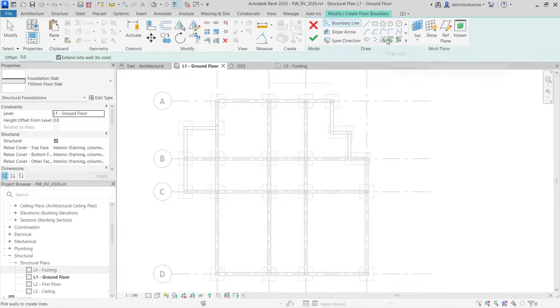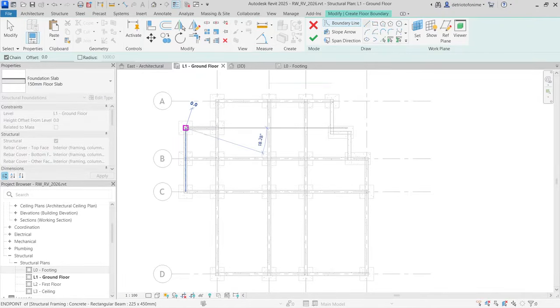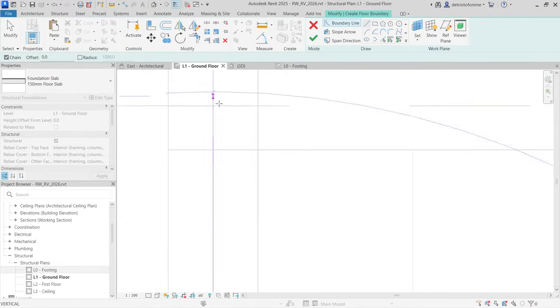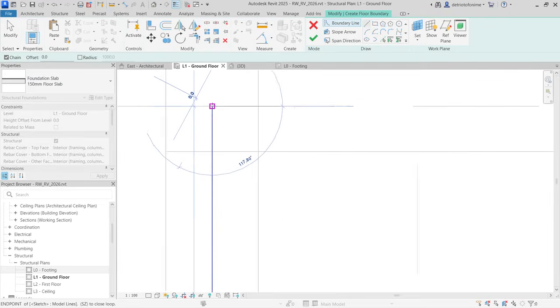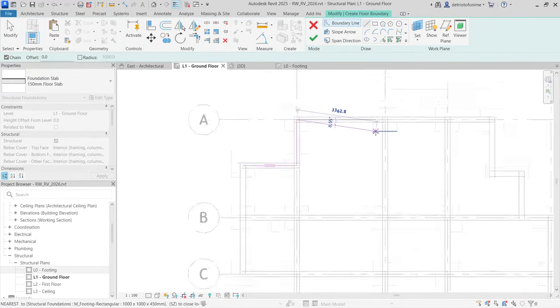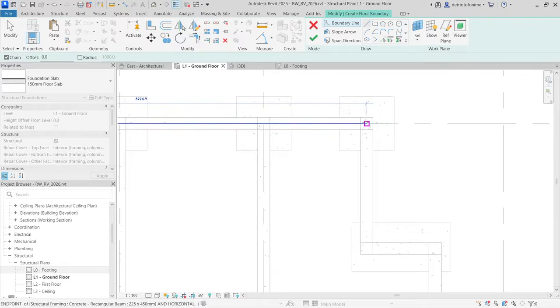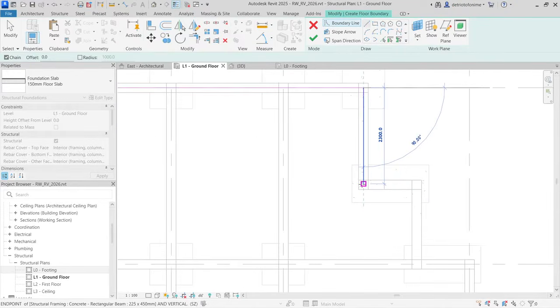Now we can draw this as a ground floor. You can use the line tool or you can use rectangles, but I'm going to use a line tool. I'm just going to start at the corner here at the endpoint. Every endpoint is going to be represented by a square. If you did not meet the square, it means you're not yet at the endpoint, where you can guess like I just did. And then to go all the way to the endpoint, select that,